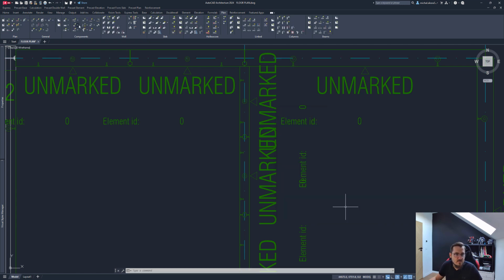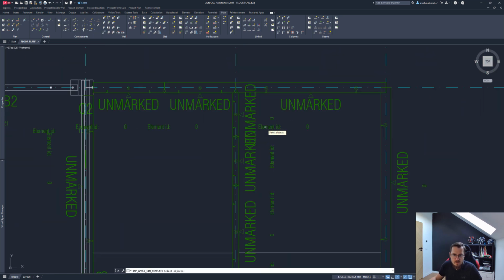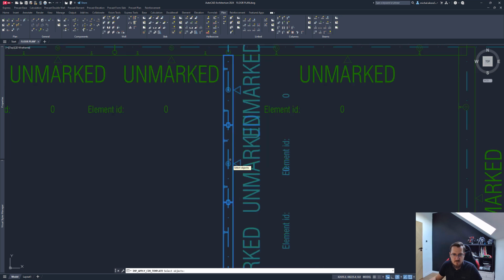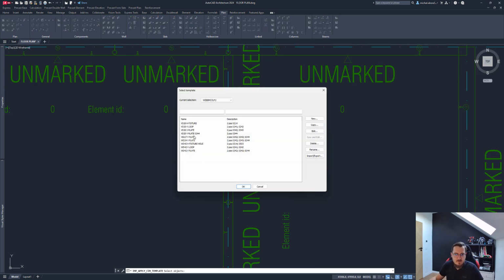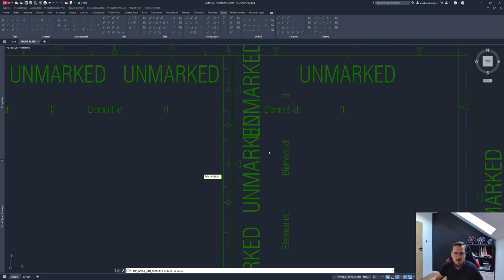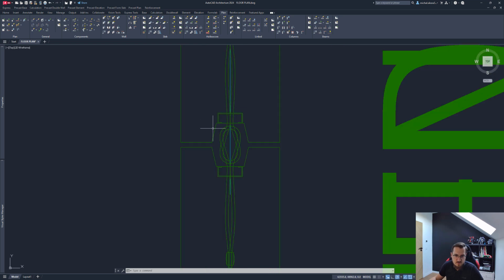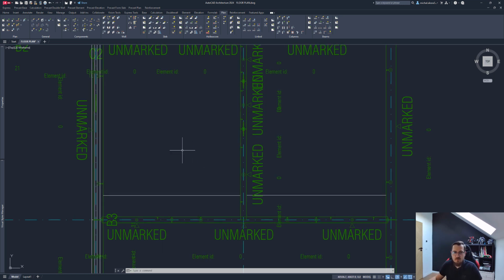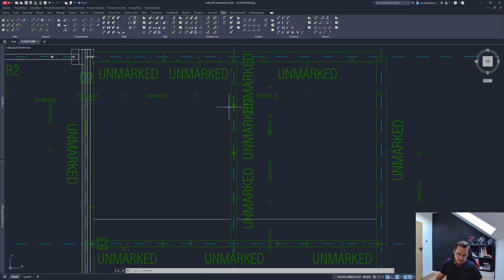Now I'll apply that template. I will select objects, those 2 walls, since I have those two types of splits here, and I'll accept that. Then specify which template to use. I want this one, and as you can see, the program automatically created the connections between those two walls. The other way of doing that would be manually. That's casting material templates. We can select multiple walls or multiple elements in the project, and the program will automatically look for any types of end caps that are defined in that template and apply the casting material that's added to it.